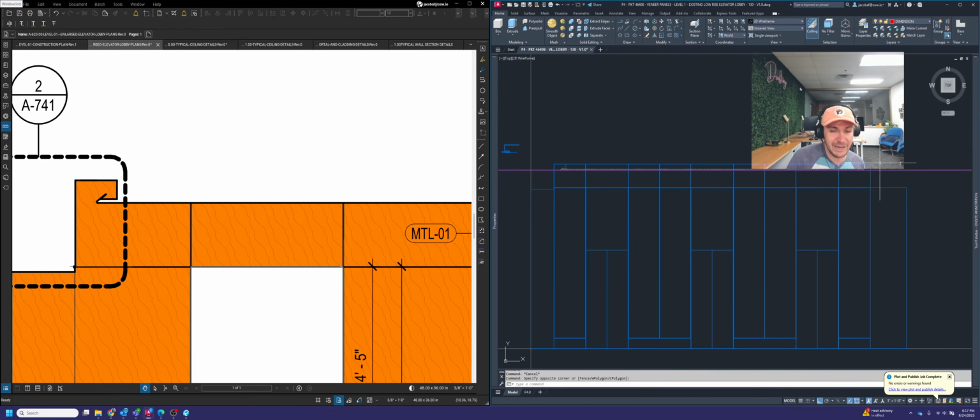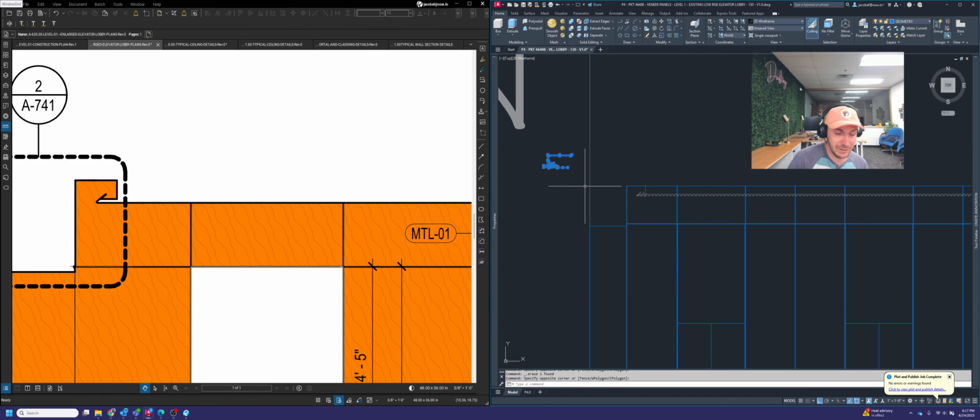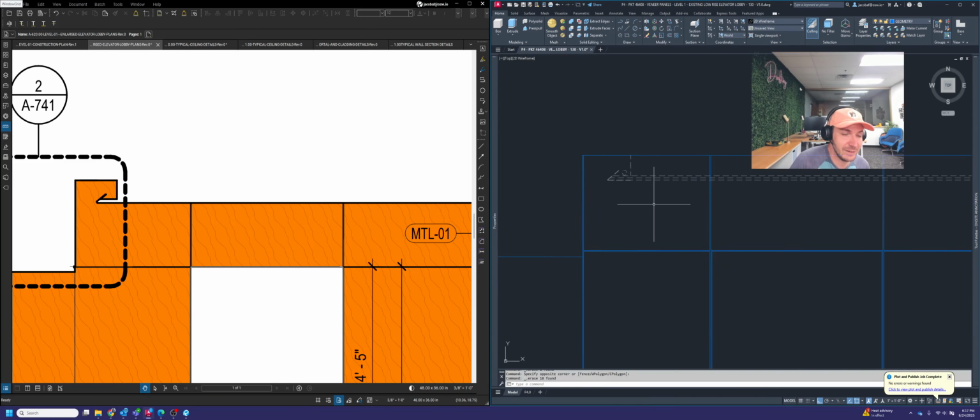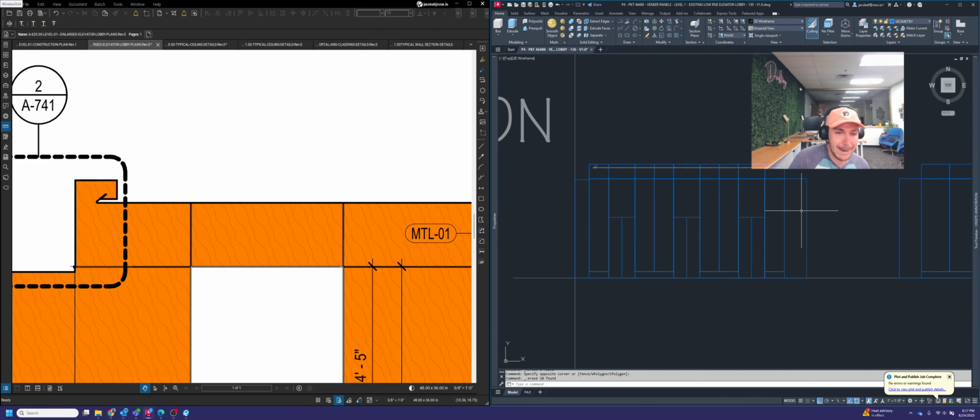So I'm going to go into my properties pane and I'm going to select hidden 2 for the line type. Then from there, I actually don't need that red line anymore. That was to represent the ceiling height. Now that I have that in the drawing, it's not important anymore. I can delete that. Actually, I don't really need that anymore either. That's now no longer needed.